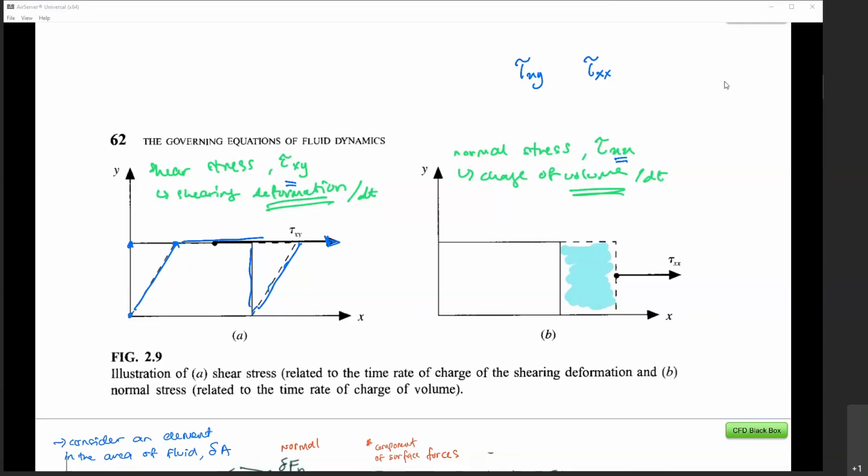In some literature, however, they want to differentiate between the shear stress and the normal stress, so they use a different notation, the stress symbol sigma, so sigma x. But do not be confused, as long as you understand that the subscript here is the important one. Just keep in mind that sometimes you are going to see normal stress being used as tau as well, but most of the time the literature wants to differentiate the shear tau from the normal sigma.